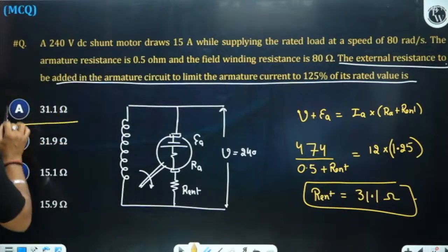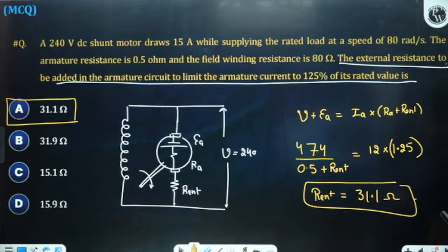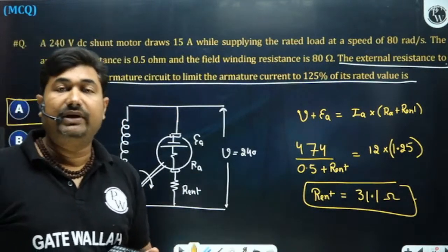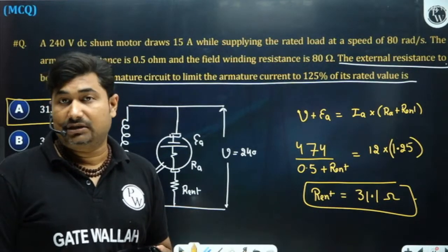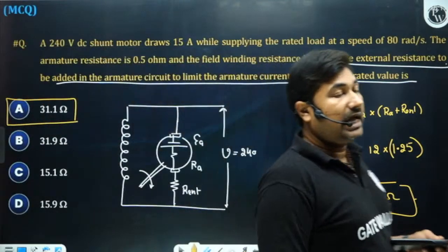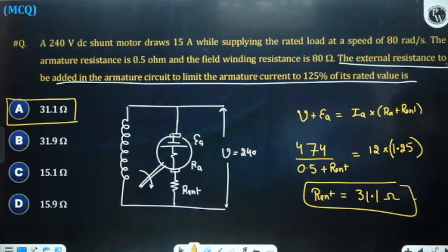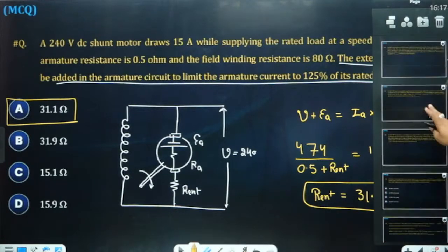So if we put this resistance, how many of you are able to understand? Does the motor behave as a generator? No. Motor is not behaving as a generator. Motor will draw very high current, and there is a very massive copper loss at the instant of plugging. That is why plugging is not suggested for high inertia loads. For a high inertia load, regenerative braking will be more preferable. Is it okay? Yes, sir.